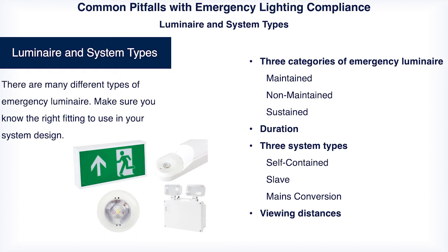When there is an emergency, then a maintained light switches over to its battery power supply. And so the light source that's in there, typically these days it's LED, would now be running a much reduced output because it's only got 12 volts worth of battery power supply to give it an output.